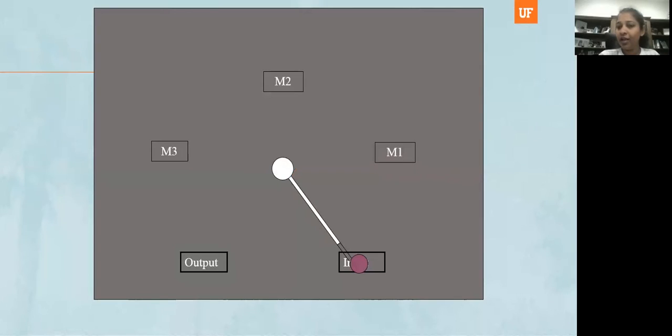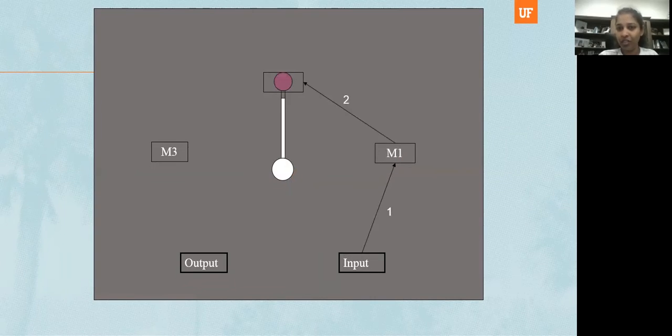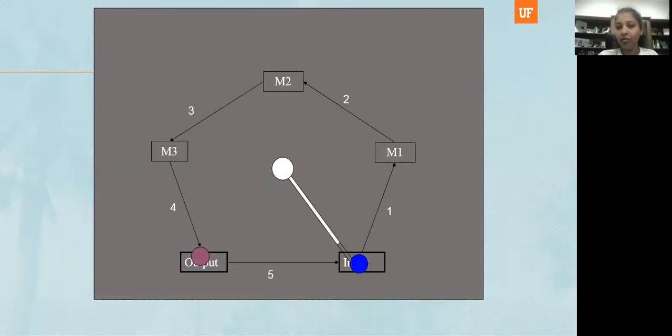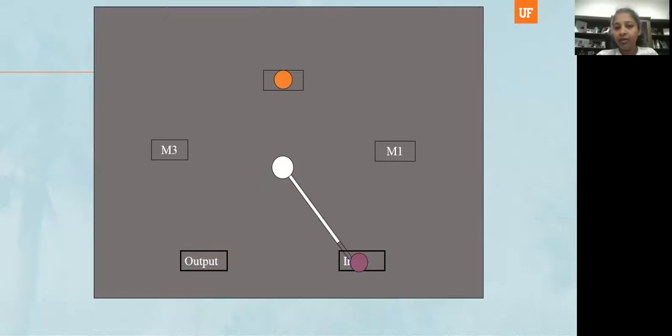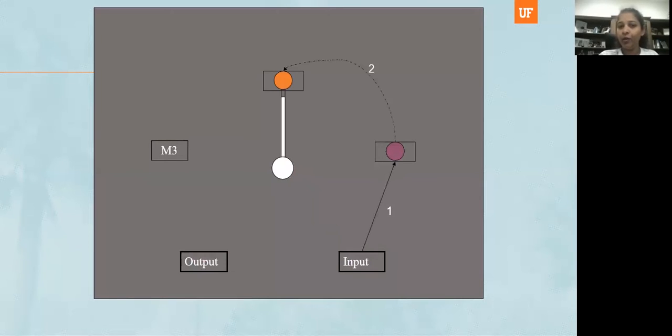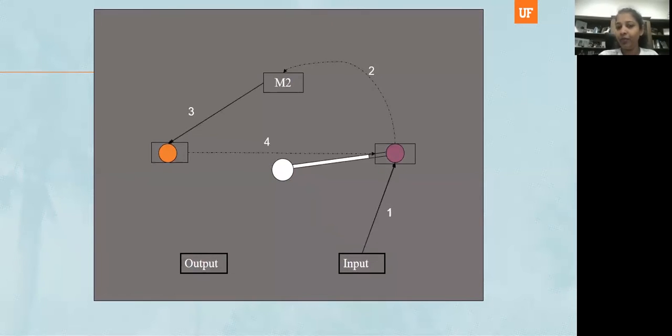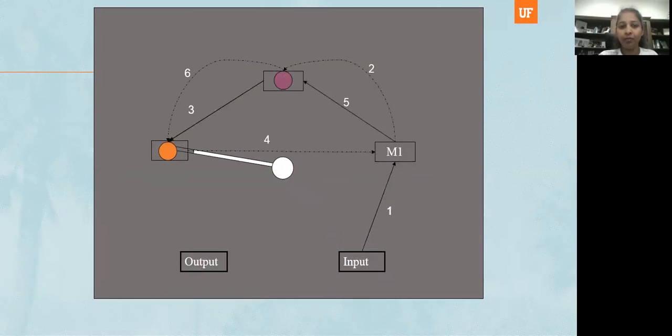So the very first cycle says, simply load a part, wait there, unload it, load the next machine, and then just follow the part. Stay with the part. This is the forward cycle. This is very simple. The second cycle says, first load the odd machines, then load the even machines.